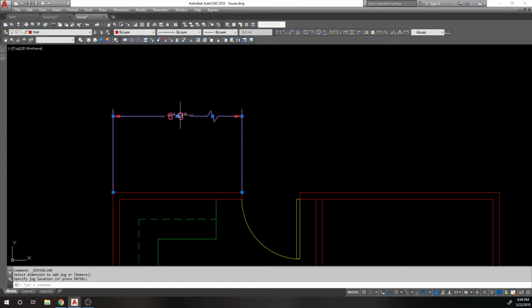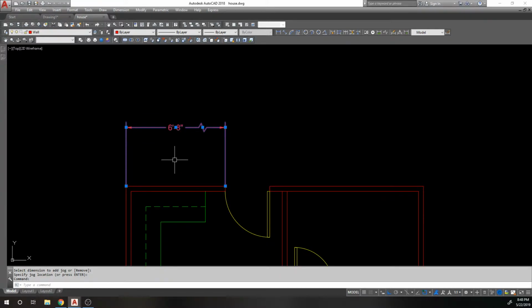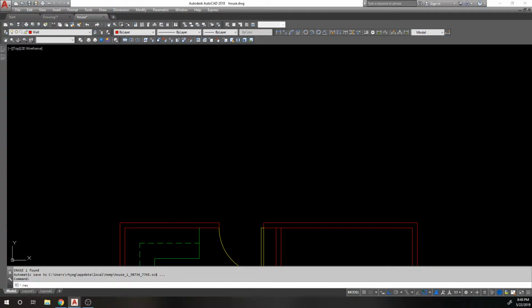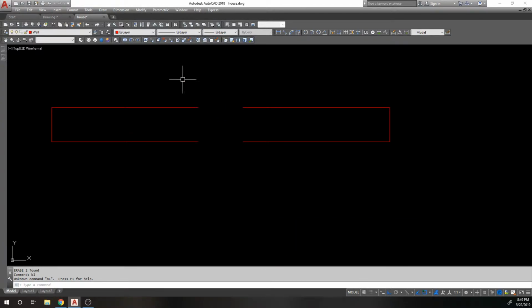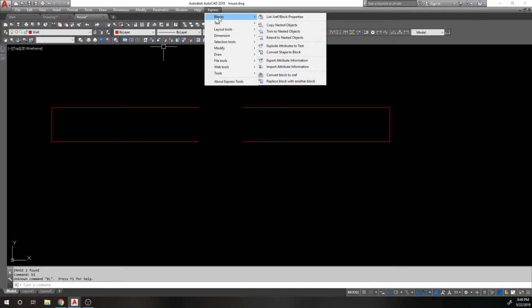And what that's for is for like, if you have something that's broken up, like let's say I have a wall, okay, and I do another wall. Is my snap tracking turned on? No. Actually, I should just copy this. Okay, right, and I got like this, and let's say that there is a break here. I'm going to explode these, erase this, and my break line, no, I don't want to draw one.